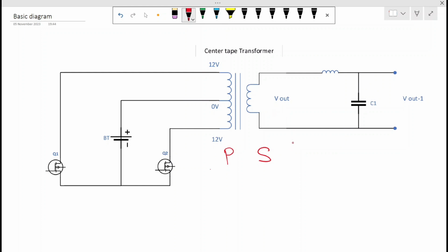So here the secondary output voltage will be 230 volt RMS and the primary voltage is 12 volt, which we are giving with the help of a battery. We have taken a 12 volt VDC battery here, just as an example; whatever voltage of battery you have, based on that we have to design the inverter transformer and get the output. So this is the 12 volt battery.